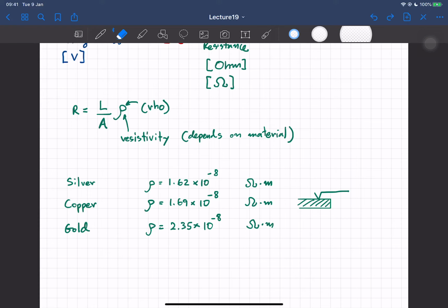But if you're not careful, the surface of this material can form what we call the oxide layer around the surface. So this is the oxide layer. An oxide layer is usually, again, an insulator. So it's gonna make electrical contact a lot worse if you don't do anything to it.